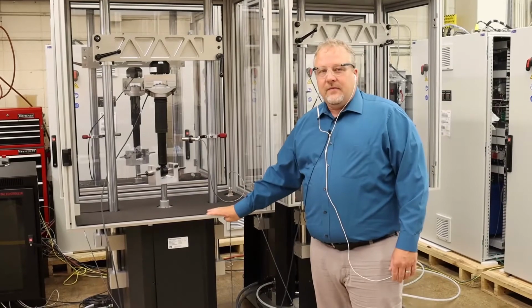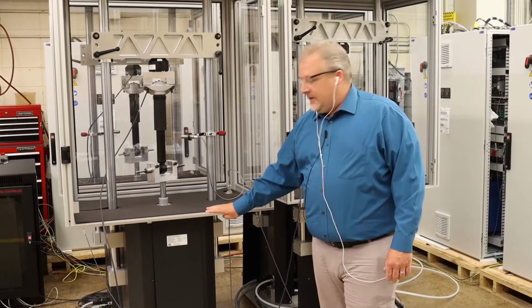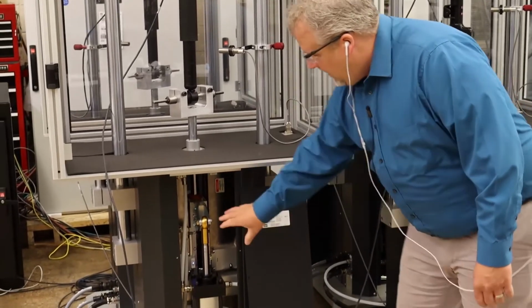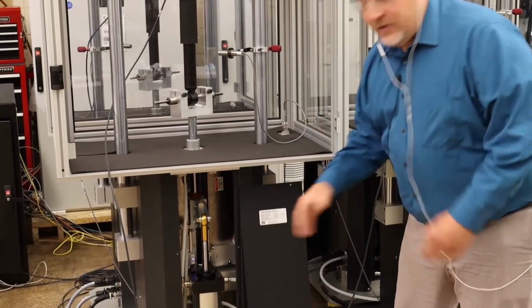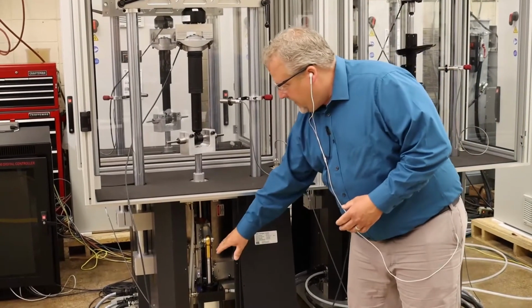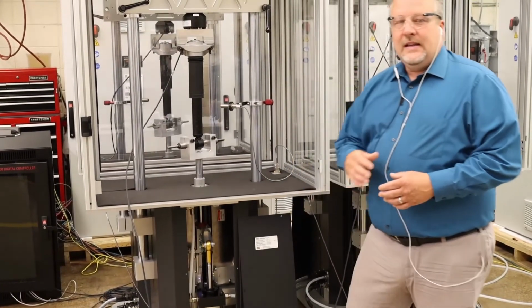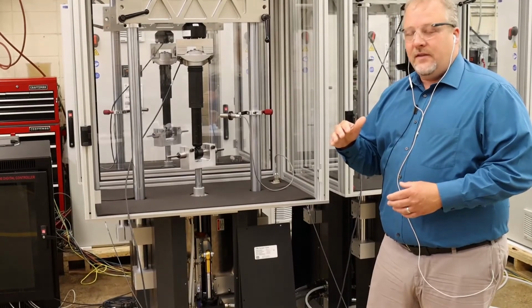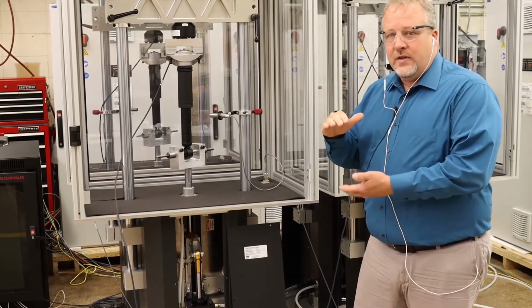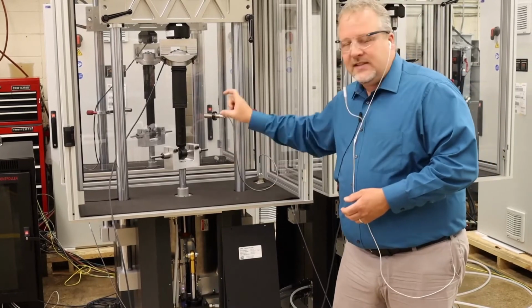Within the EMMA electromagnetic actuation damper frame itself, we have the EMMA electric actuation device down here, which has a high-speed displacement feedback encoder as well. And shown in the front here is a static support cylinder. This is to offset the mean force if you have springs installed on your dampers or on your struts, to offset the mean load that those would apply, so the electric actuator only has to move the dynamic load.